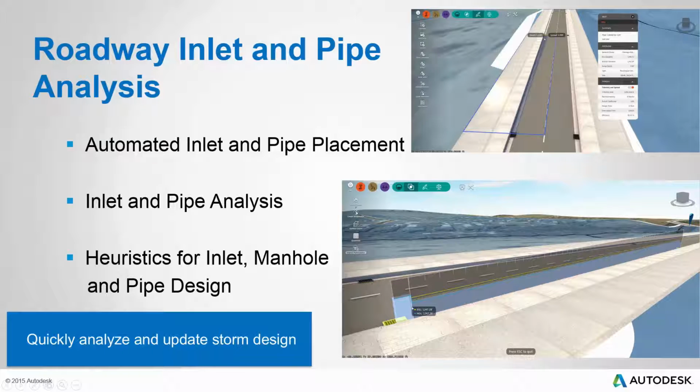You're able to control inside of the asset card how close you would like it to typically add inlets. So if it's 300 feet, it will add inlets every 300 feet until it sees inside of the watershed that it needs to add an additional inlet, and then it would override that 300 feet. This number can be 300 feet, 400 feet, whatever you would like it to be.